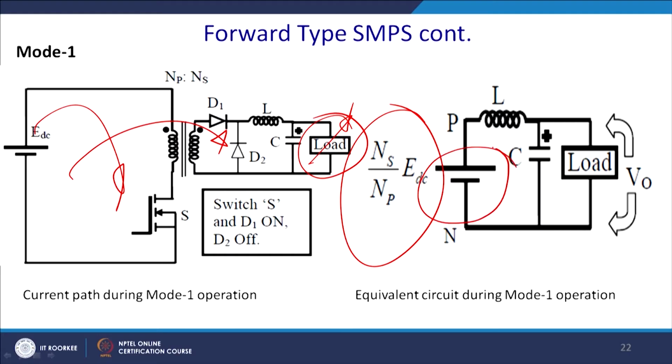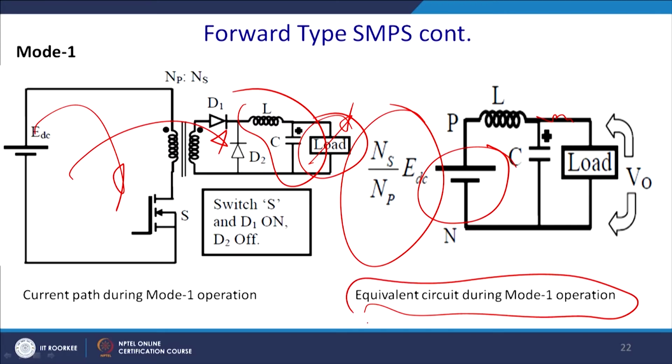So, this is the effective DC bus voltage, and this part of the filters comes into the picture. Of course, you can use a T filter sometimes, a pi filter also, some kind of filter may be used to get better results, because you have here a 40 dB decay, you can increase that decay further.